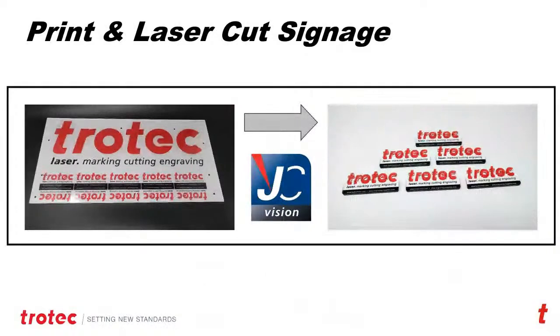And so once you've printed your graphic, you can see here the different graphic. Here are the little black dots around the Trotec logo. Those black dots are registration points, and we typically use just a 1/4 of an inch circle or smaller, ideally just around a 1/4 of an inch in size, and then send that to the printer.